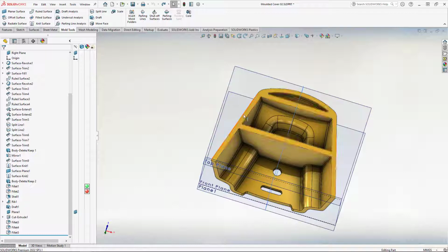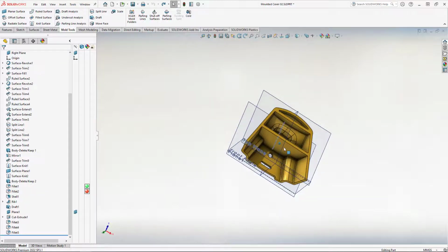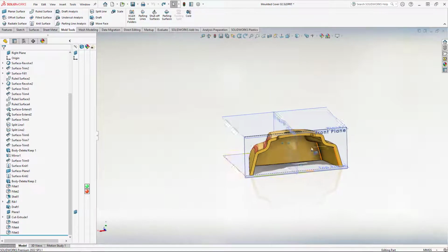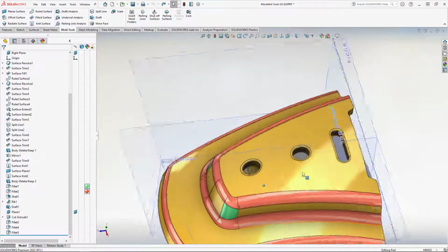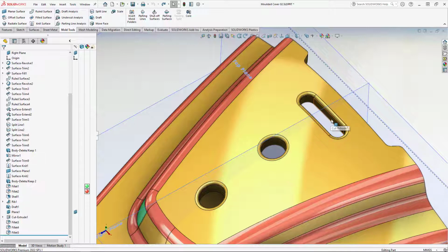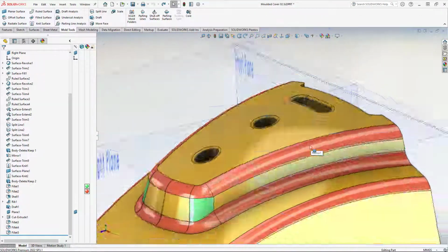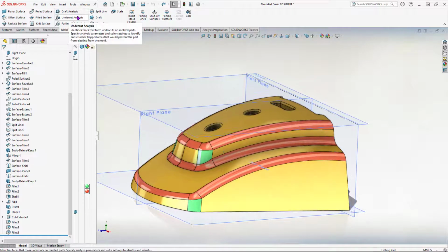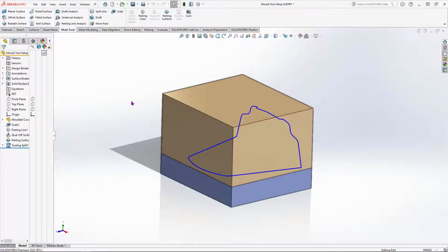It has a thin outer wall, it has some faces missing, it has some rib features. It has draft angle on most of these surfaces to allow easy removal from the mold, and it has these through cuts. So it has 3 cuts or cut features that go all the way through the finished part. So that's the part that we're hoping to mold, and just to familiarize ourselves with some of the terms and the process, I've already completed the mold for this particular part.